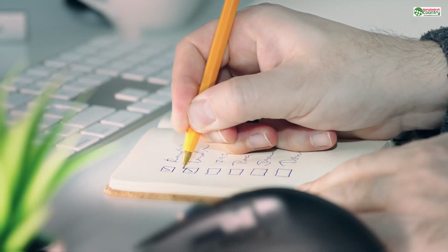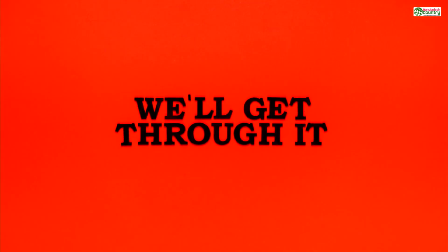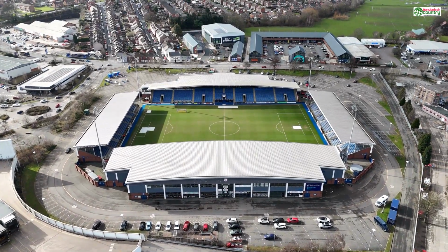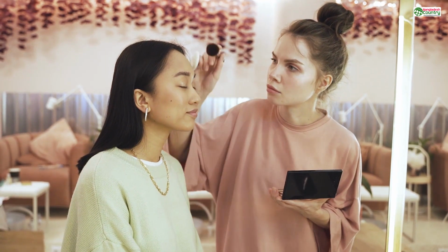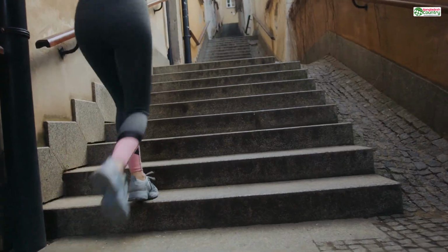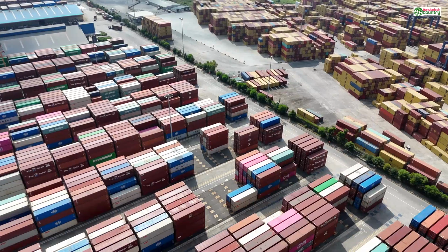Let me explain why. Sometimes in 3D software, you can scale an object visually without actually changing its base data. It's like putting a magnifying glass over it. It looks bigger, but the software still remembers its original, smaller size. Ticking that Apply Transform box forces the software to bake in that new size. It makes the visual size the actual size. Forgetting this step is one of the most common reasons why a perfectly scaled model in your software suddenly imports incorrectly into the printing service.